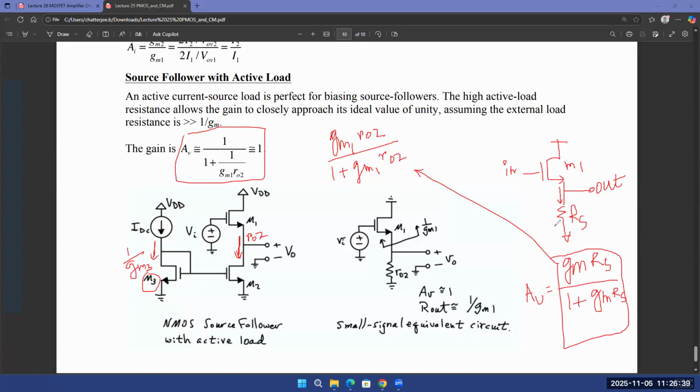So this might not be very clear at this point, but generally a resistor or a capacitor within an IC technology takes a lot of area. Whereas a MOSFET can be very small. You know that MOSFETs can be scaled to nanometers. People are talking about single digit nanometer or going beyond 1 nanometer as well these days, right? So MOSFETs can be very, very small. So you can implement a very large resistance, ideally infinite resistance, just with one MOSFET.